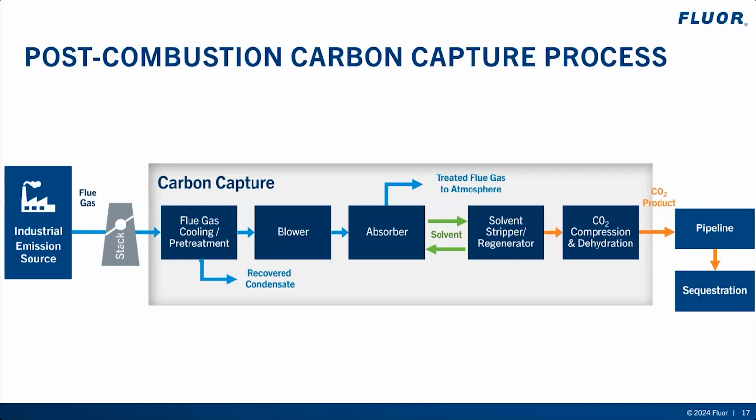Colder absorber temperature profiles favor thermodynamics and the CO2 loading capacity of the solvent, as well as reduce volumetric flow rates in the absorber, while warmer absorber temperature profiles improve kinetics and the associated rate of CO2 absorption. These competing effects act to counterbalance each other, providing some flexibility in the design to accommodate a range of acceptable cooling temperature profiles while still meeting the overall CO2 recovery requirement.